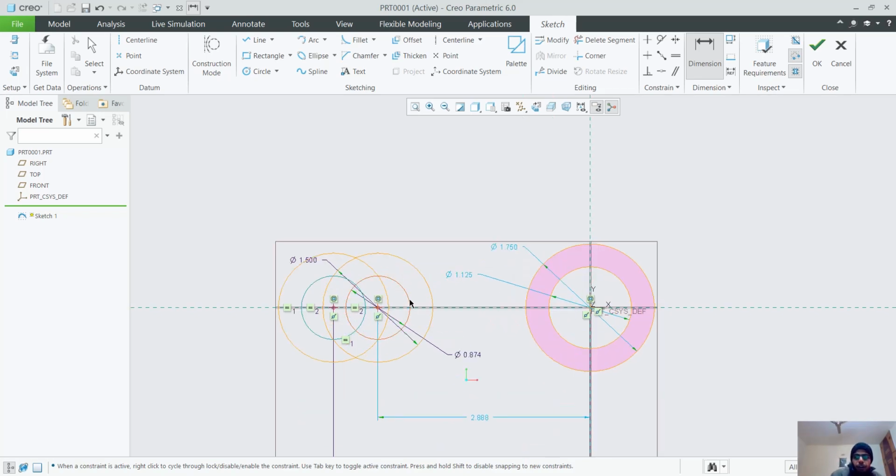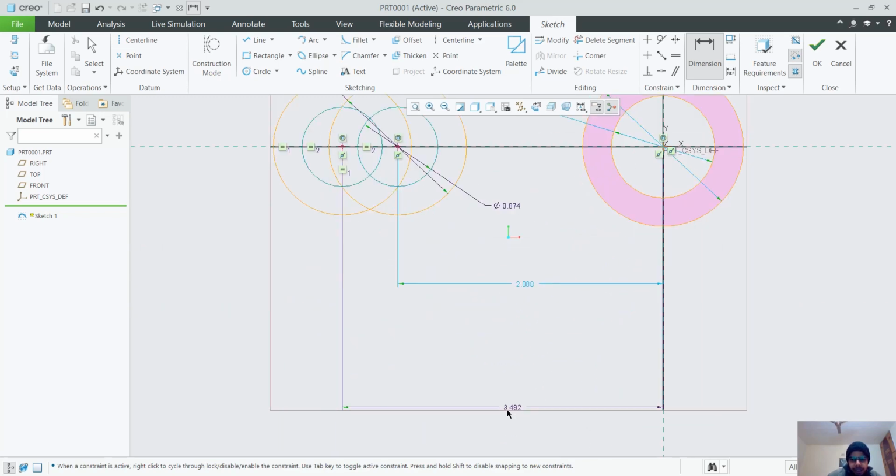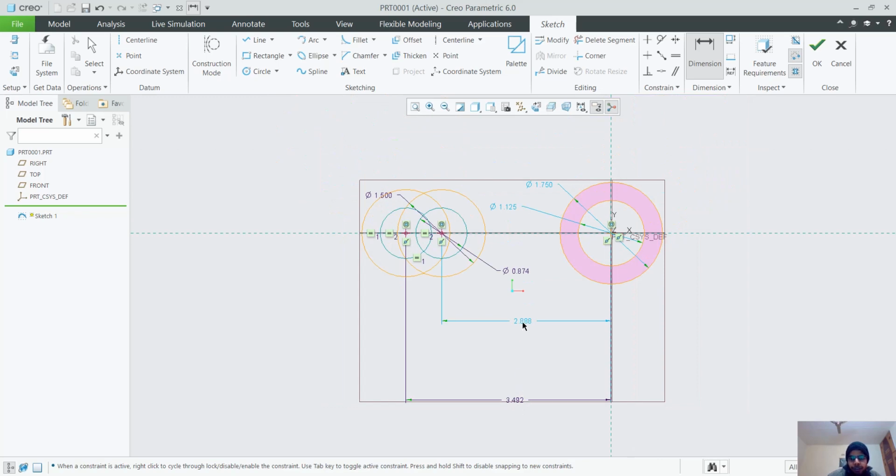All the dimensions that we want to give are center aligned, meaning every dimension is going to be from the point here. So this is 3.492 and minus 1. I want to make this dimension 1, so minus 1, and I can click escape. Minus 1, 2.492. Alright, now it's done like a good boy.